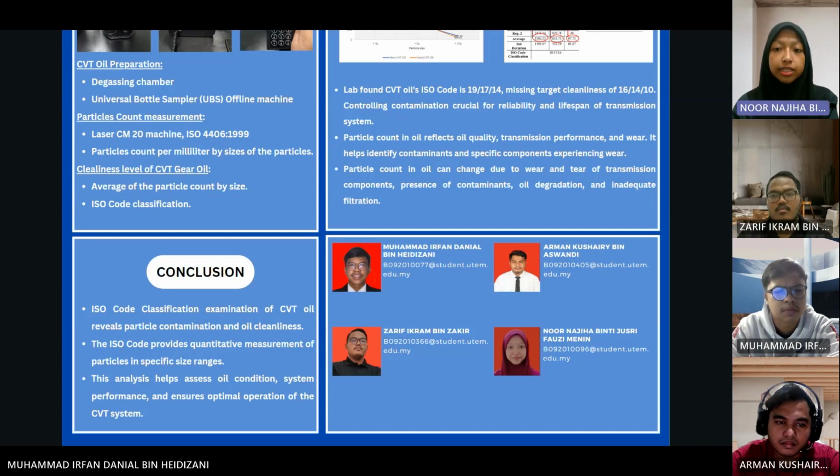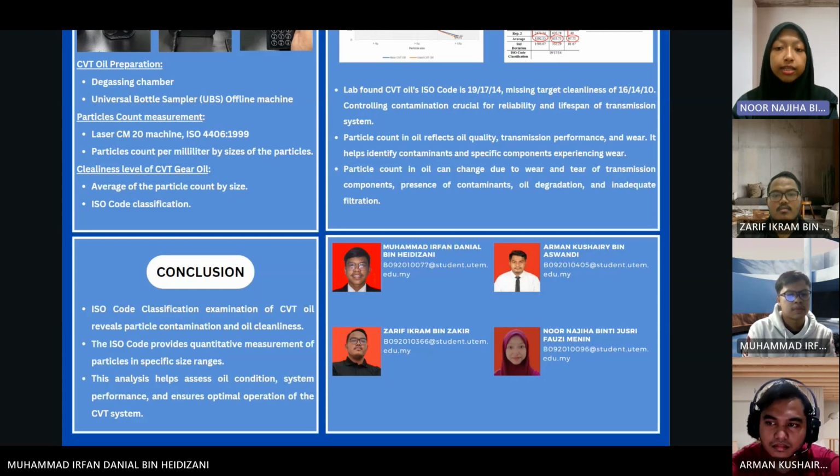Machine components that experience friction and contact will produce wear debris regardless of the presence of lubricants. Particle count data plays an essential role in a proactive condition monitoring program as it serves to guarantee minimum component degradation and determine the cleanliness level of hydraulic fluids for dependable operations.